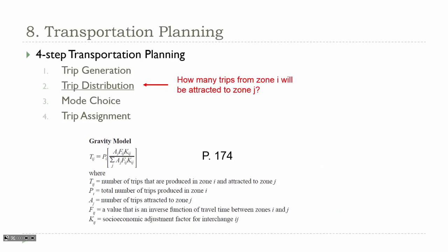Transportation planning. We're on the home stretch. The only two I think that I'm going to talk about. So trip generation, there's not really anything they can give you because this is where you use the chart. Like for a gas station, how many pumps are there? If there's 3 pumps, we're estimating the total trips being generated. I guess they could give you that chart and ask you to do some calculations, but hopefully you can remember how to do that. So trip generation, assuming you have the city broken down into different census tracts, is trying to estimate how many shopping trips are going to be generated from one zone going to other zones. And so the gravity model is what we can use to estimate those particular trips.